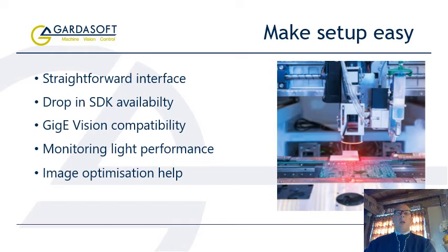The controller should incur minimal delay between the trigger signal and the light pulse, and Gardasoft provides controllers such as the RT-CC range, which have inbuilt timing functionality for applications requiring more sophisticated timing, such as configurable delays and multiple triggers, and also setting up triggers for the reject systems. The system can be set for either an external signal to trigger both the camera and the lighting controller, or for a signal from the camera to trigger the light.